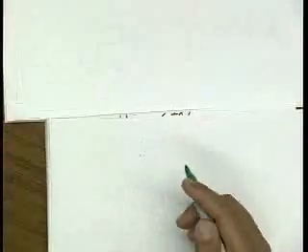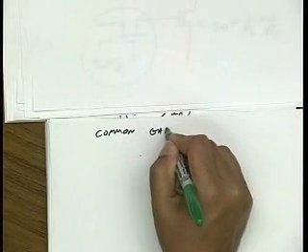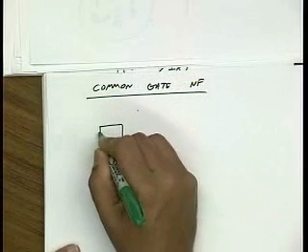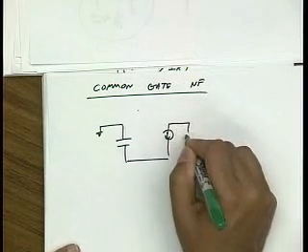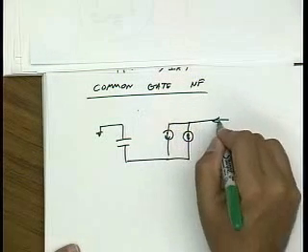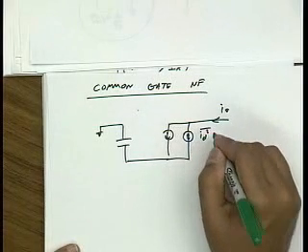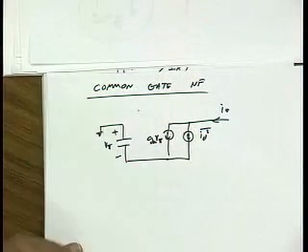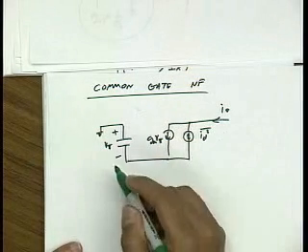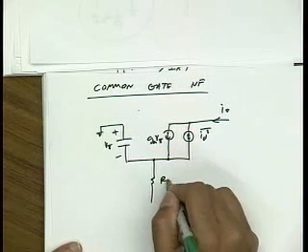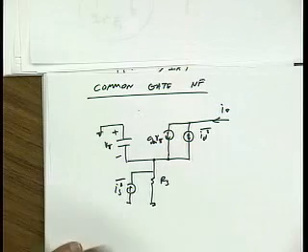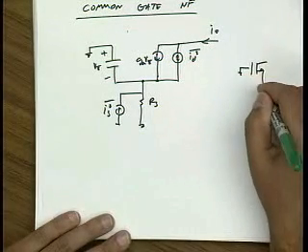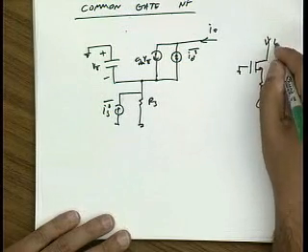All right. So let's first of all do the common gate. And I'm not going to make too many simplifying assumptions. I'm just going to do the problem fairly completely. So I'll find the total output current where I have drain noise. And another important assumption is that you're told to neglect gate noise. Okay? So that makes the problem a lot easier too. That means that for my FET, the only noise source is ID. And I have RS and IS. So this is the equivalent circuit that I have to solve. In other words, this is the equivalent circuit for VS, RS, I out.